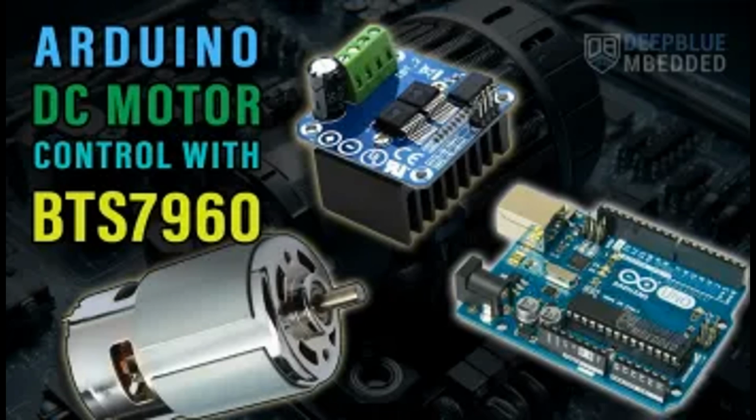Summary of key features. Commutation methods. BLDC motor drivers use different methods of commutation, including 6-step and sinusoidal commutation. Sensor-based or sensorless control may be used. Feedback control. Drivers can use Hall sensors, encoders, or back EMF for rotor position feedback, or operate sensorless, using just the motor's electrical characteristics. Control techniques.